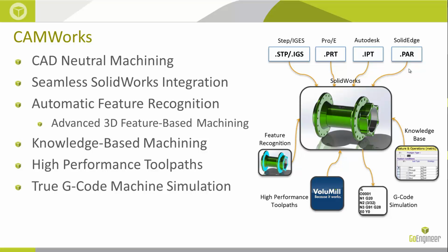So really what we need is to simulate the G-code, eliminate that translation, and eliminate that source of inconsistency or error. And that's what we can do here now: we can actually post the G-code and simulate it in a machine simulator. So again, it's not only simulating the part, but it's simulating the entire machine environment, so that we can check for interferences between, say, our tailstock and the turret, or the gang tool holder on our lathe against the stock or the chuck. It will check all of that. So it's truly an amazing product here.